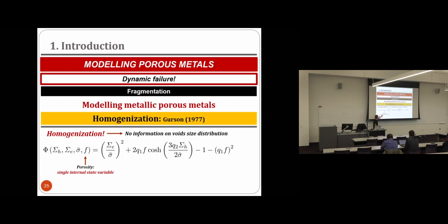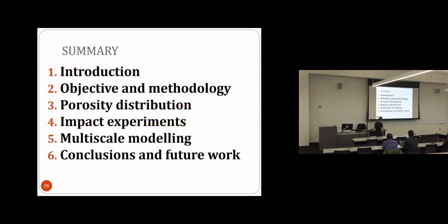problems. So what we wanted to do here is not only to use this homogenization approach, but also include the actual porous microstructure. Because the reality is that if we use the homogenization approach, we don't account for the distribution of void sizes, we don't account for the spatial distribution of voids, and so on. And we thought that all these features are important. So we are performing calculations, importing into a finite element code directly the porous microstructure that we obtain from the X-ray tomographies. Okay? And we are comparing our results with the Gurson approach. And let's see if I have time to show some of these modeling results.